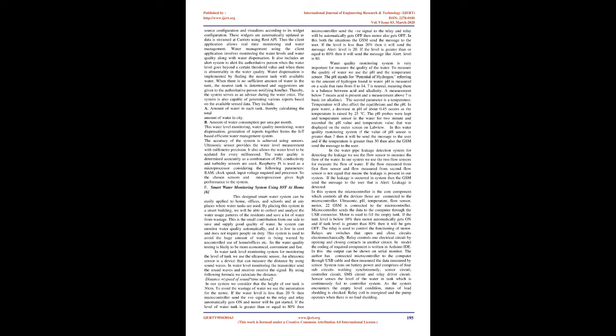In our system we consider that the height of our tank is 30 centimeters. To avoid the wastage of water we use automation for the motor. If the water level is less than 20%, then the microcontroller sends the positive signal to the relay and the relay automatically gets on and the motor will get started. If the level of the water tank is greater than or equal to 80%, then the microcontroller sends the negative signal to the relay and the relay will automatically get off, then the motor also gets off.